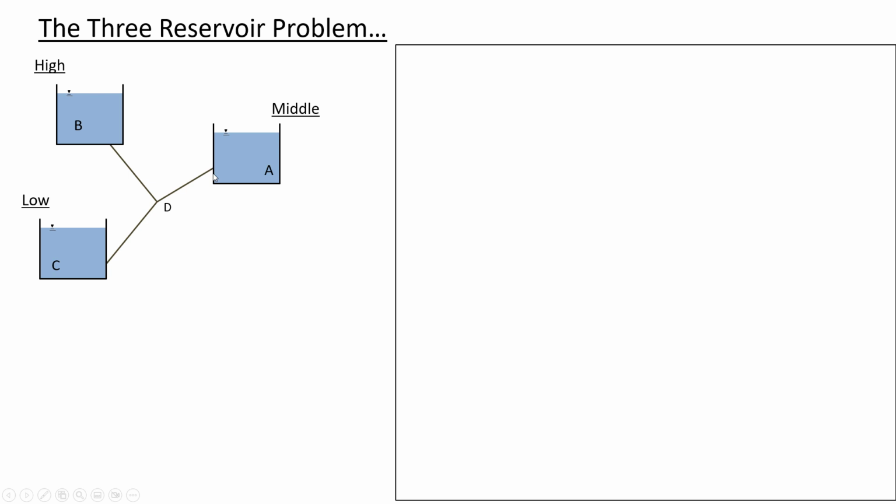It would be going out. Yeah, obviously, if both of the reservoirs are at the same elevation, then the water would be going out of the middle reservoir. The other extreme is, what if reservoir A had the water level down as low as the water level for reservoir C? Then the water would be flowing in to reservoir A.